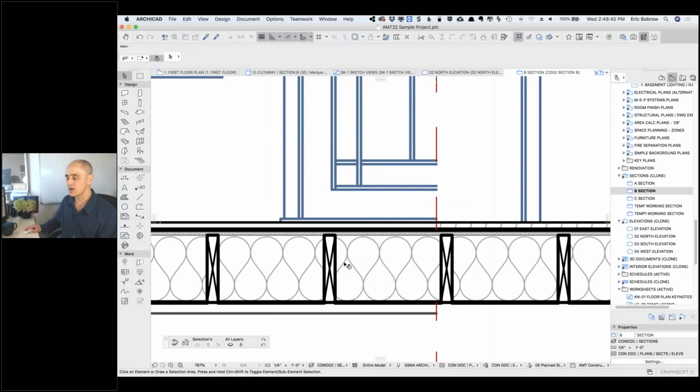So now you can see the framing here, and I was a little embarrassed after a presentation I gave 2 or 3 weeks ago, because I had the framing like this, but I had the X with the heavy lines and the outline lighter. And to my naive eye, I thought that really looked good. But I can't remember who it was who was polite enough to set me straight and say, architectural graphic standards, the outline of something you cut through is what you want to show with a heavy border, not the interior X, etc. So I made it heavier.